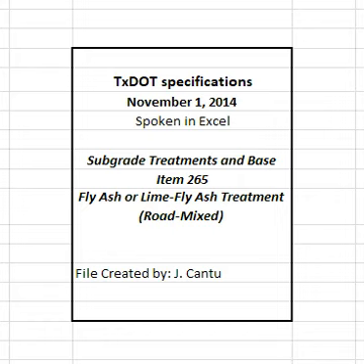Pulverize or scarify material after shaping so that 100% passes a 2.5 inch sieve. If the material cannot be uniformly processed to the required depth in a single pass, excavate and windrow the material to expose a secondary grade to achieve processing to planned depth. 4.3 Application and mixing of FA or LFA.